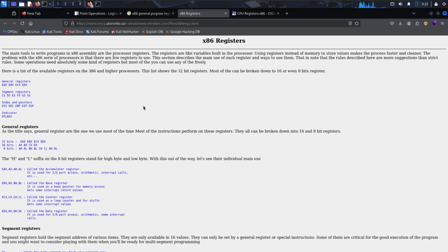These are the lowest level, well, there are lower levels, but this is how we communicate with our CPU. We have different registers built for different things, and the breakdown comes around general purpose registers, the segment registers, and the flag registers, which have carry flags on them, and then we have the pointers.